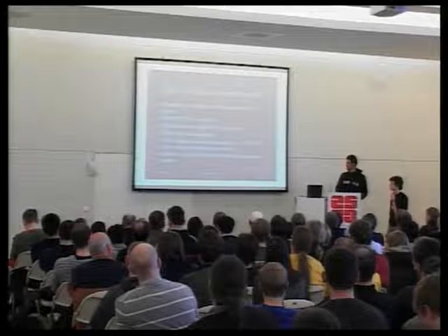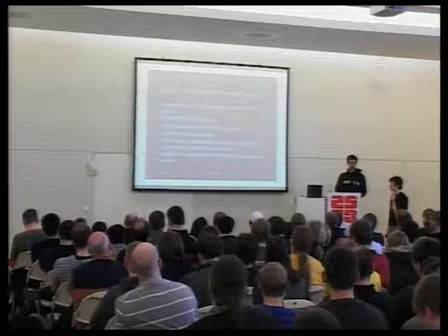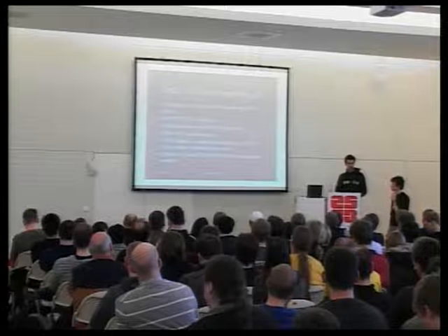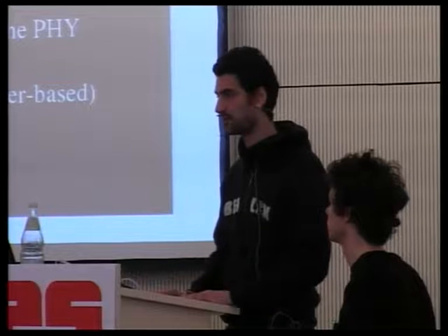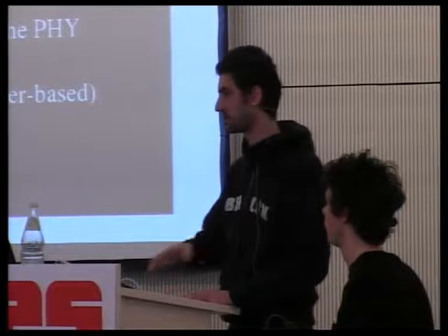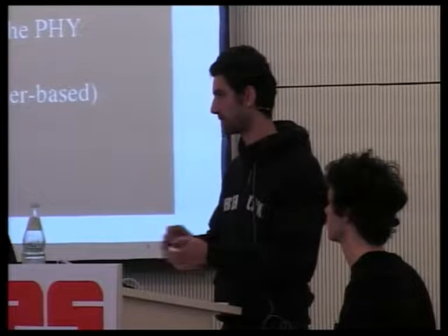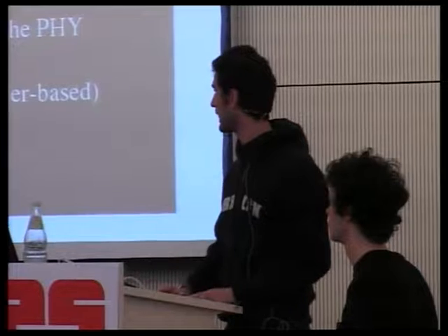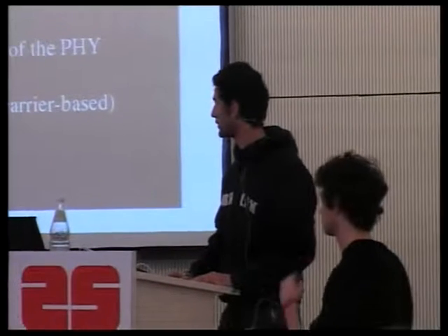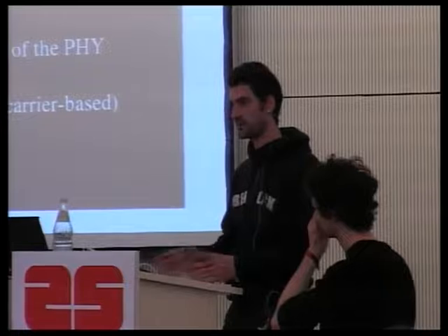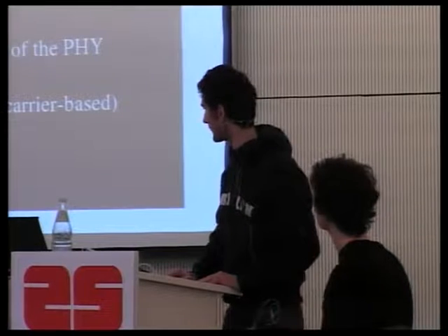The architecture, like I said, is one coordinator. There is an automatic election of the coordinator. When you plug in your devices, one device will be elected by the others because it's well located on the electrical network, so it can interact with all the devices, and the others will be in station mode. So you can refer to a kind of master-slave architecture.